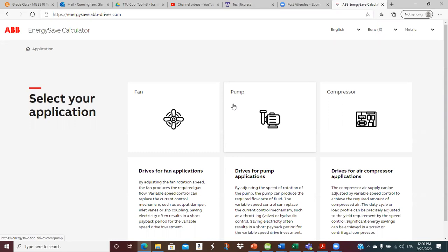Okay, and a variable frequency drive allows this fan to run with speed control. It's an electronic device, a power electronic device that basically changes the frequency. It takes the input power at 60 hertz and breaks it down and puts it back together at different frequencies. And you also have to change the voltage to it, but we, mechanicals, don't really care about the internal workings of it. We care about the fact that it'll save energy for us on the fan control, okay?